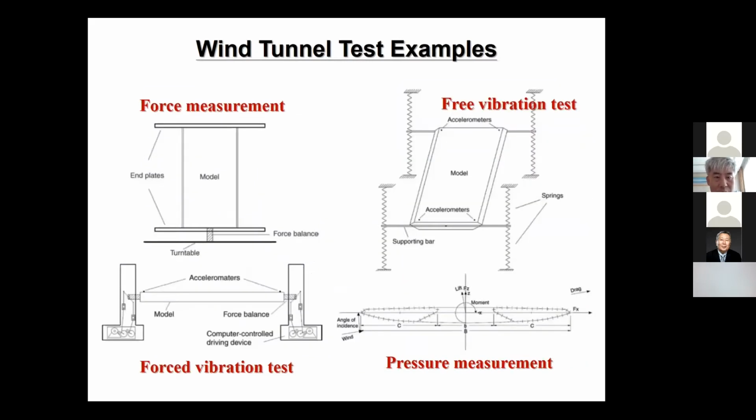Here is some example for our bridge test. It shows a clear force balance to measure the wind force on a bridge deck model. Also, you can use vibration. This one is a free vibration test. You have springs, a free vibration test for a bridge deck, and we use accelerometers to test it.